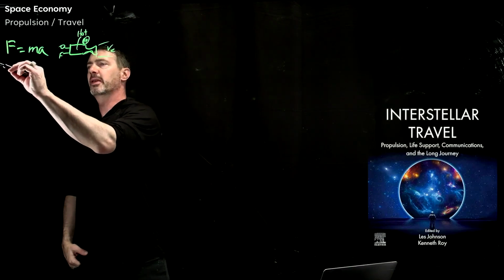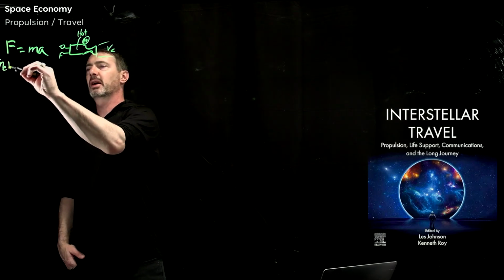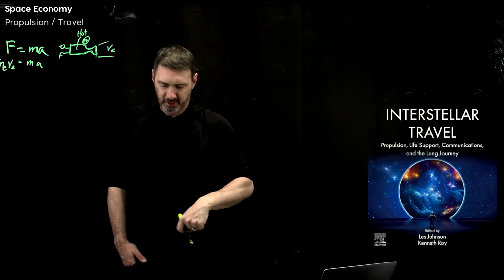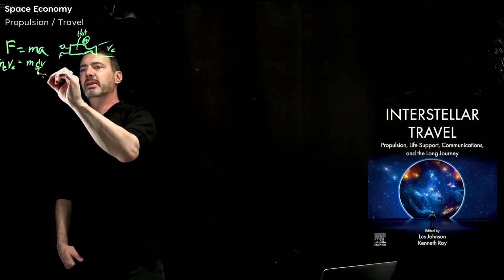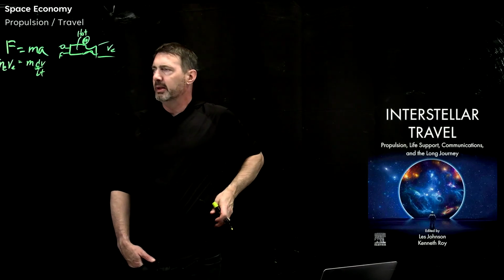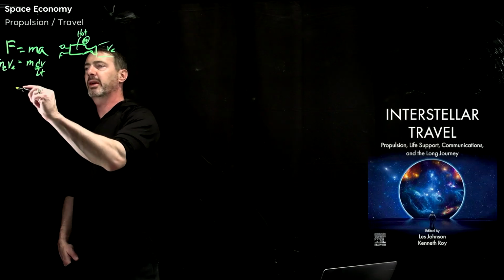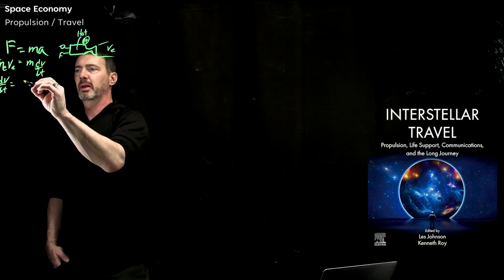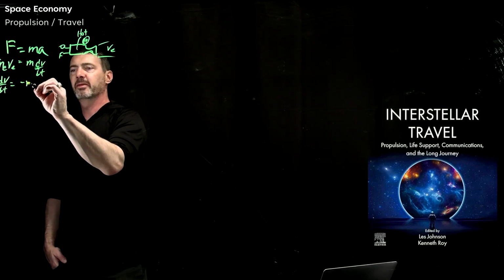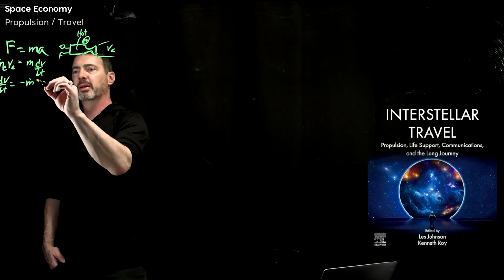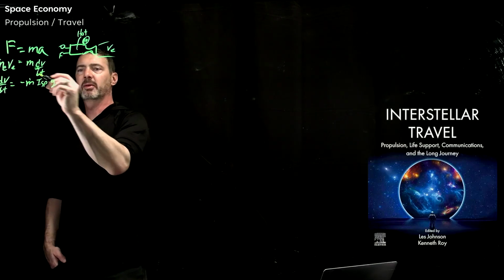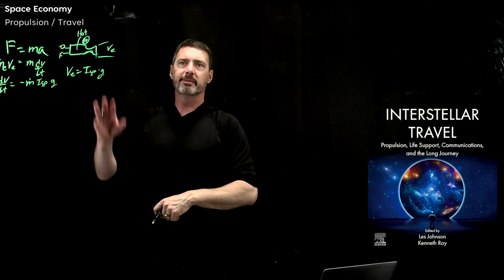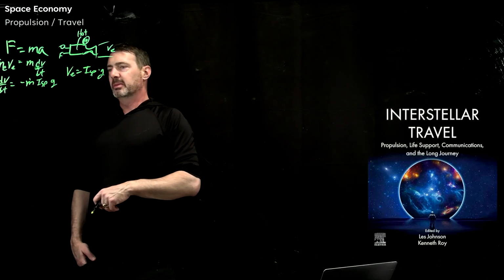And so the force on this is actually the mass flow rate of the engine times the velocity of the exhaust, and that's equal to mass times acceleration, although again, I'll switch this to dv/dt. Then you can put velocity on this side. So dv/dt is equal to the negative m dot of the rocket times Isp times g. That's normally how we define the exit velocity, Isp times g. And I'm not accounting for any pressure adjustments. This is just the basic formula.